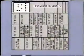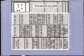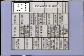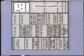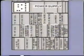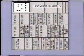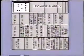Moving down the carrier panel, the next three tiers contain the modules that make up the radio part of the carrier, both transmitter and receiver. This includes oscillators, which set the transmitter and receiver frequencies, modulators and demodulators to mix or demix voice and other audio signals, amplifiers, filters for outgoing and incoming signals.